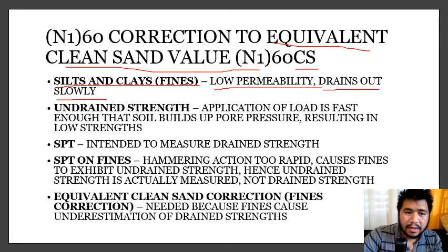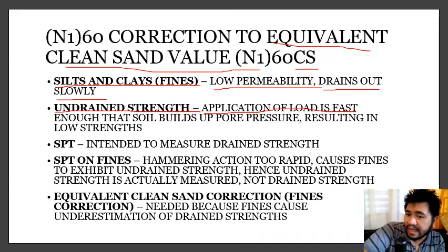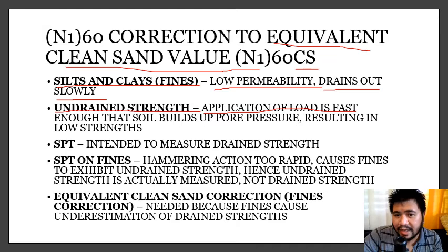Now we have what we call the concept of undrained strength, and this happens when the application of load is too fast. For example, in the SPT, when you're hammering the soil, you're actually applying the load very fast.